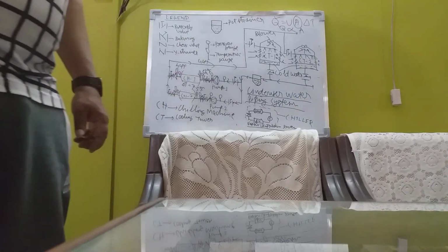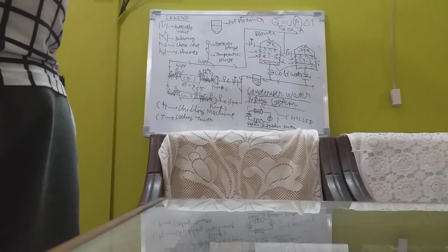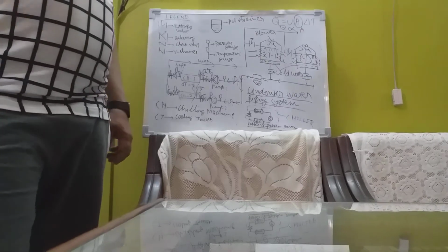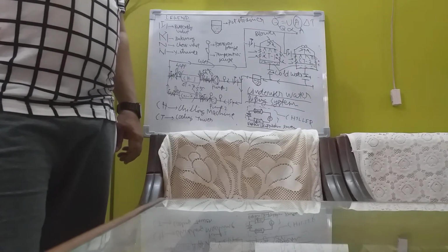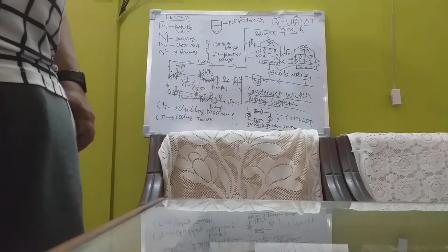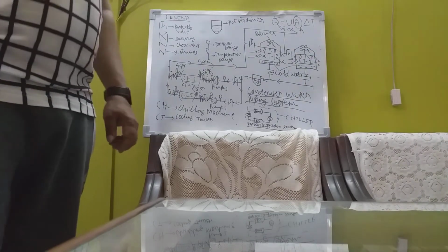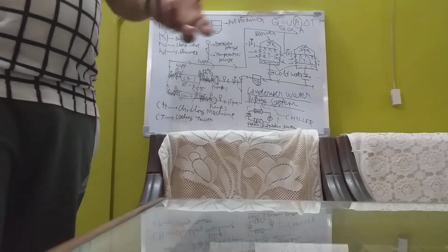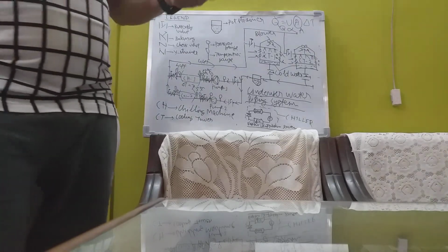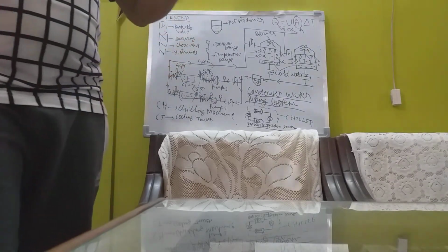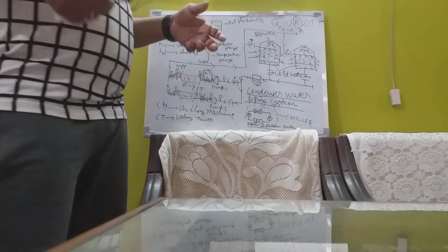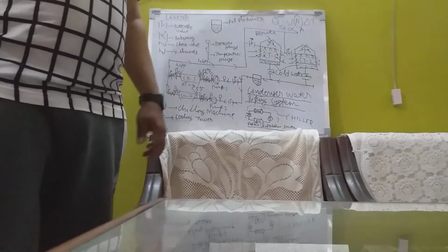In case of air, the cooling is less, because the air itself gets hot in the summer. Water does a better cooling. But in Gulf, there is no option, so we do air cooling. And when we do air cooling, the temperature of condenser increases.